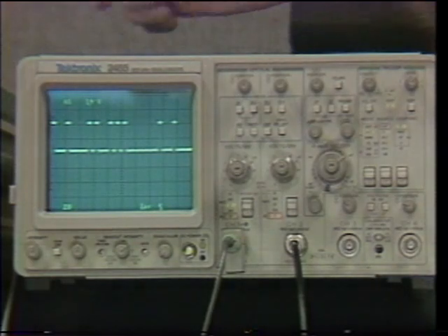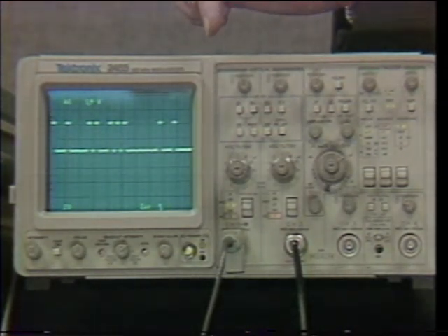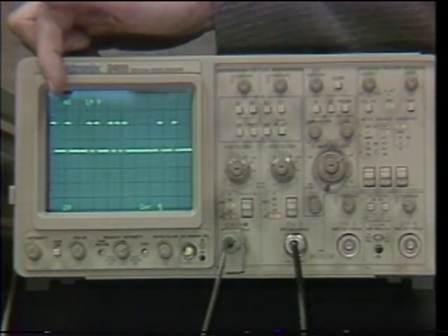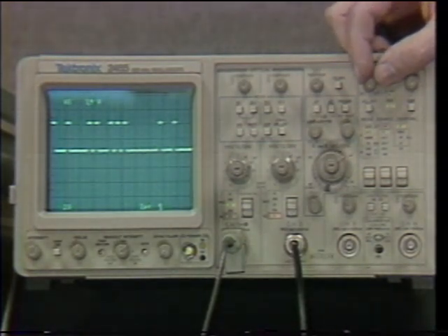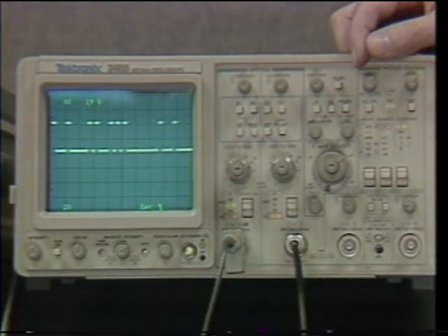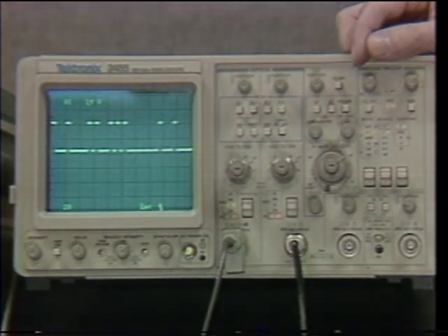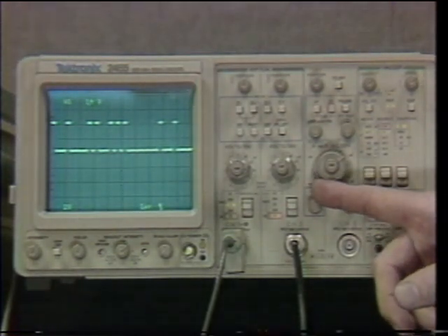The time cycle for the sweep comprises the time that the sweep takes to move the beam across the CRT, a short time that elapses while the beam is retraced back to the starting point, and then an additional time which is adjusted by the hold-off control, which in this case forces the trigger to wait until the beginning of the next cycle of this irregular sequence of pulses. One advantage of the 2465 and 2445 hold-off control is that it provides a hold-off time which is at least equal to the sweep duration time for all sweep speeds faster than 100 milliseconds per division.